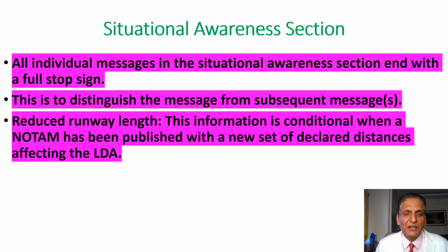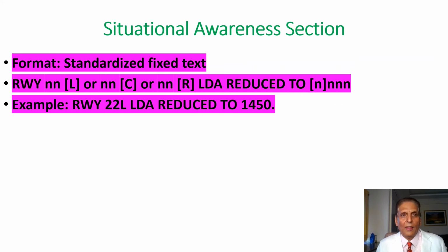In the situational awareness section, please remember all individual messages will end with a full stop sign. This is to distinguish the message from subsequent messages. Reduced runway length: this information is conditional when a NOTAM has been published with a new set of declared distances affecting the landing distance available. Format will be standardized fixed text. This is the format. Example: runway 22 left, landing distance available LDA reduced to 1450. This is how it has to be shown.